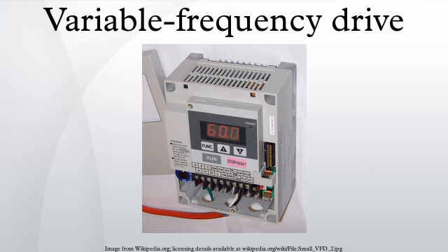Dynamic braking wastes braking energy by transforming it to heat. By contrast, regenerative drives recover braking energy by injecting this energy on the AC line. The capital cost of regenerative drives is however relatively high. Regenerative drives. Regenerative AC drives have the capacity to recover the braking energy of a load moving faster than the designated motor speed and return it to the power system.